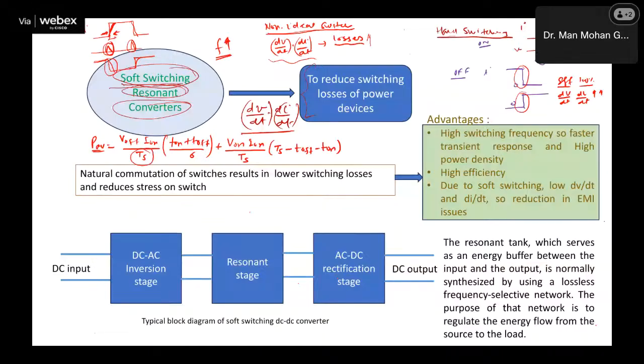Here, this switching loss is proportional to Fs. Now, when this is proportional to Fs, it means I cannot increase the switching frequency to be very high. And here, the conduction loss is not dependent on switching frequency, but V1 and I1 are high. So basically, this conduction loss, whatever it is, will be there and cannot be reduced. Our aim is not to reduce that. Our aim is to reduce switching losses and dv by dt and di by dt. That is our aim.